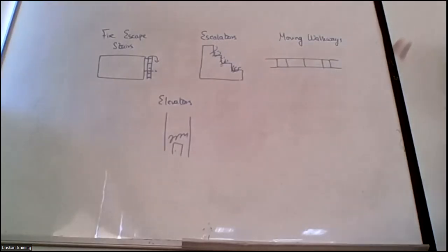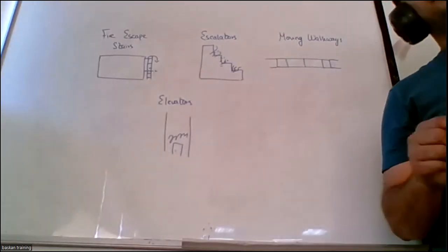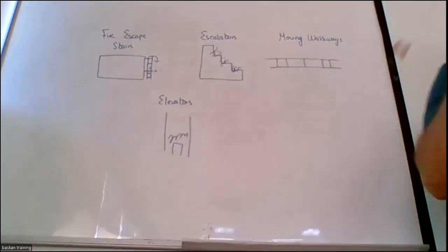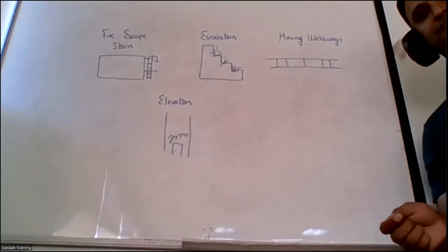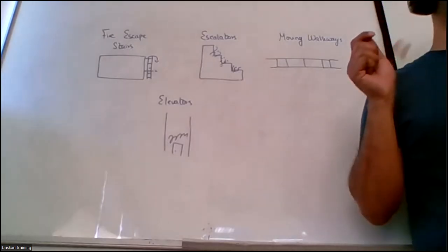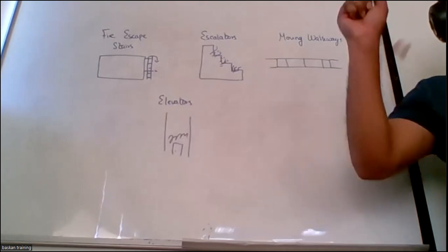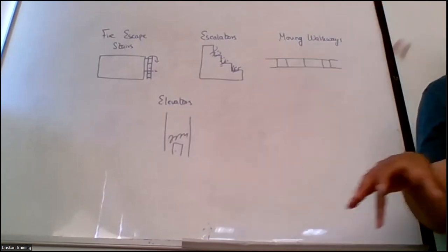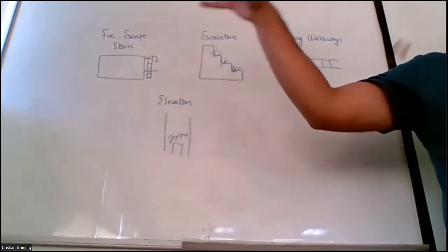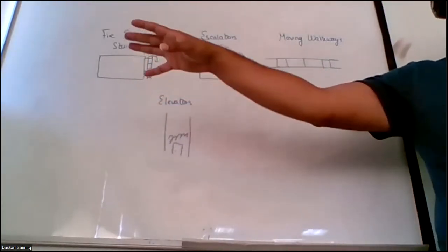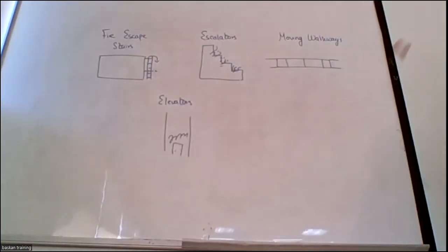So if a door is opening to the outside of the building, either on the grade level, but it is taking you outside of the building, meaning it's separating you from the building, that component is known as exit. Okay, so exit discharge is not any type of component. You cannot say it's a material itself. Exit discharge means your position in the public way. You are standing on a footpath in the streets, completely isolating yourself. That is exit discharge. So when you're talking about a component, it is exit.